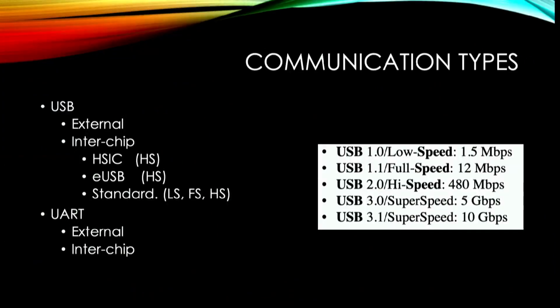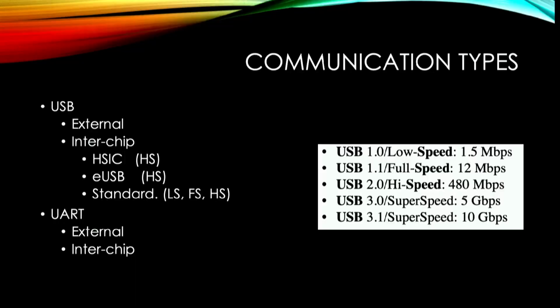When we're dealing with cellular IoT devices, now this may be different on higher end devices, but on these devices you have two typical communications. You have USB, you have UART. They almost always have two UARTs. I want to mention that. One of them is a debug UART. So you can plug into the debug UART. It's mostly available, and you can watch the chip boot up.